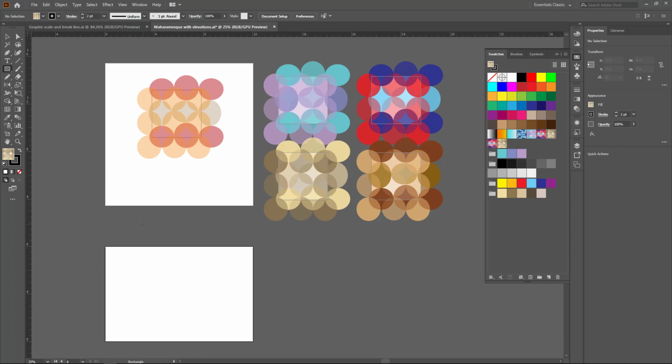I'm going to draw an elevation at 1/4 inch scale, maybe 10-foot high ceilings, I don't know, about 24 feet wide. Well, at 1/4 inch scale, you just divide those numbers of feet by 4 to get the dimension in inches. So that's going to be about 6 inches by 2.5 inches high.